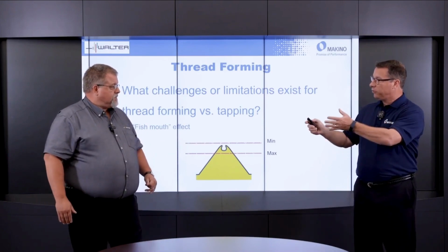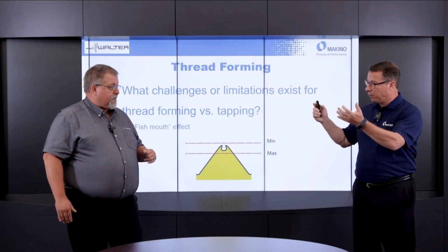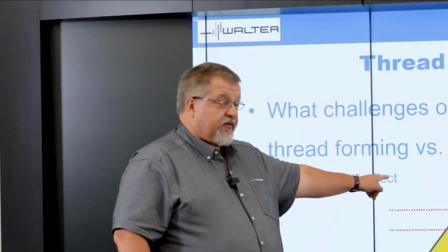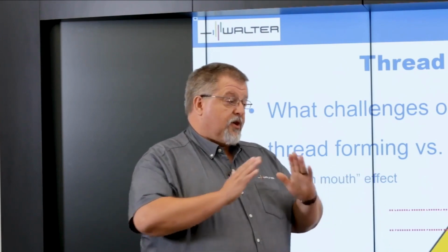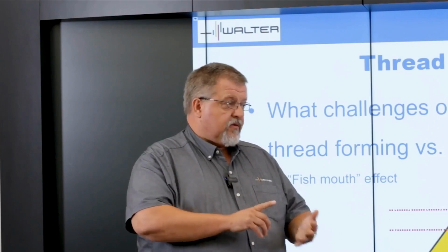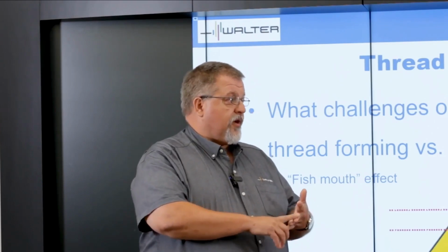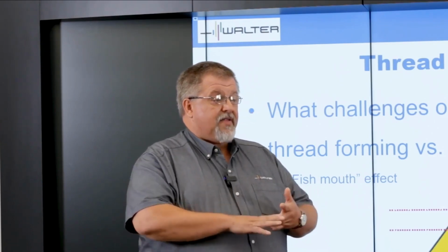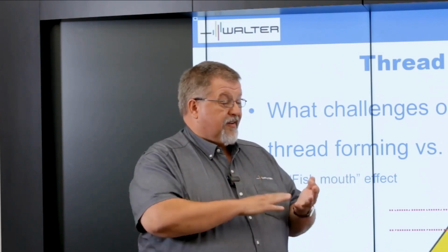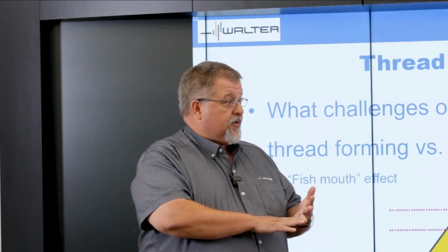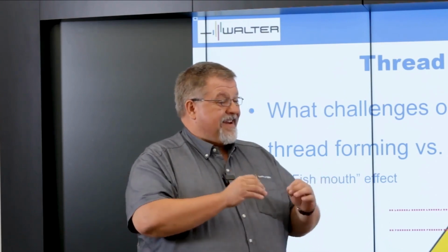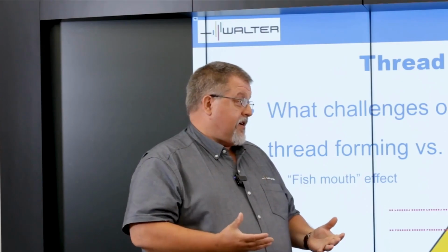Okay. Implications of that from the standpoint of industry acceptance? Very good question. This fish mouth on top here will create a cavity where you can keep contaminants: coolants, cleaning solutions, rust preventative. If we would use thread forming in the food industry or the medical industry for implants, it might not be very good. It's not that we really can't get it clean, it's just that you can't prove you're getting it clean.